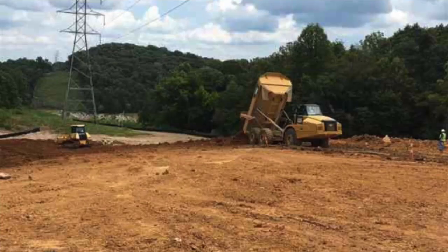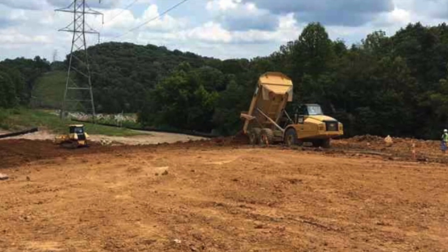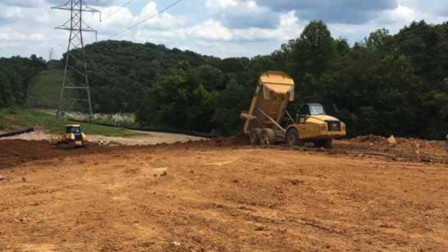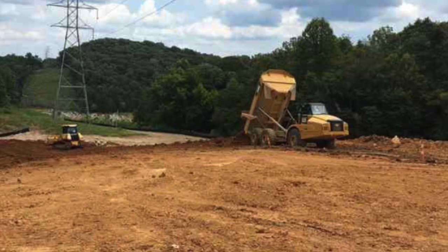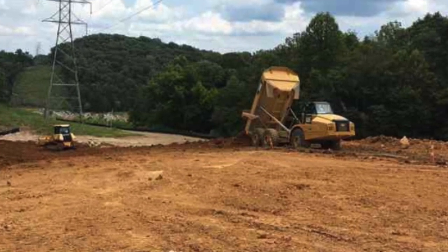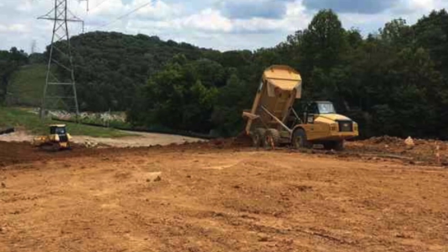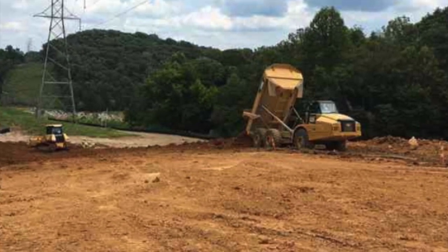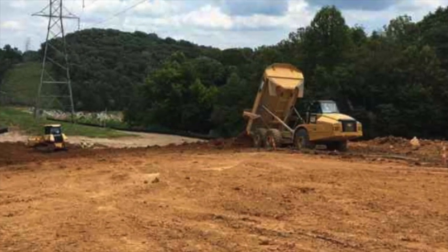Before constructing, the area on which an embankment is to be placed should be cleared of all vegetation, such as trees, logs, stems and roots of trees, etc., and other objectionable material which cannot be properly consolidated or will not support the load of the embankment or structures.